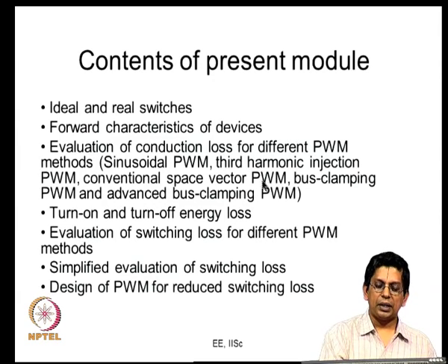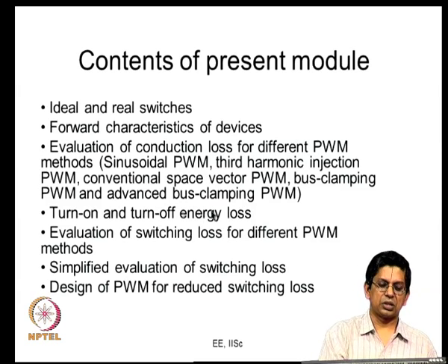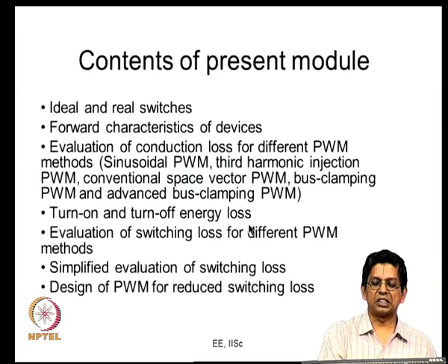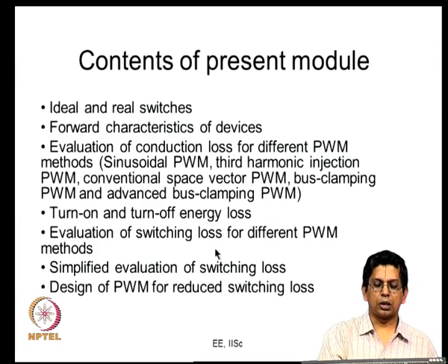Then we will look at the turn on energy loss and the turn off energy loss. When a device is turning on or turning off, that is, in one leg one device turns off and the other device turns on, there is a certain amount of energy lost. We will get into such things in greater detail in the next class. This lecture would focus more on the conduction loss part.